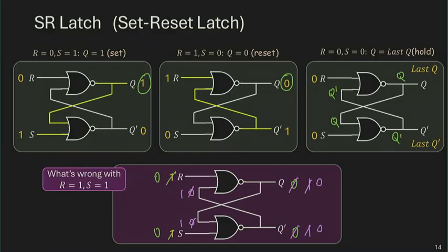And this will just repeat forever. 1, 1 becomes 0, 0, comes back to the front, becomes 1, 1, and it never stops. So you run into an unstable condition after using the 1, 1 inputs and then switching to the 0, 0 input. When Q and Q prime are not complement to each other, you cannot reasonably hold it. And that is a danger with them being non-complement to each other. Therefore, with an SR latch, those three conditions are valid use of the latch. The bottom condition is an invalid use, because we might run into some indeterminate behavior afterwards.